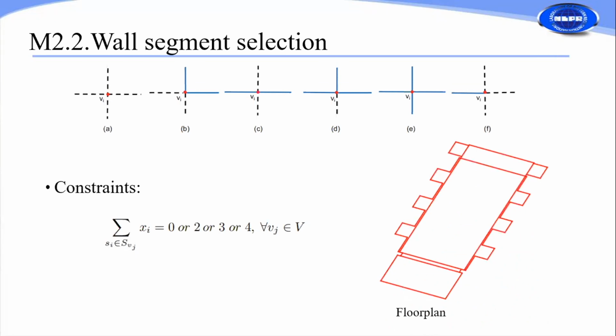For the scenes where the wall point cloud is relatively complete, the floor plan here is enough. But if there are many missing areas in the wall point cloud, especially in MLS data, the results here may not be ideal. For these scenes, we hope to use the ceiling and floor point clouds to help the generation of the wall model and obtain the complete 3D results. Then we can project the wall model onto the ground to generate a better floor plan.